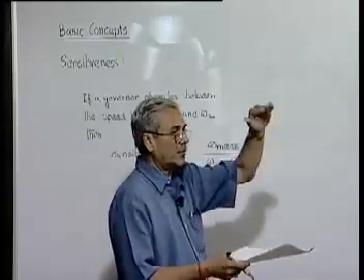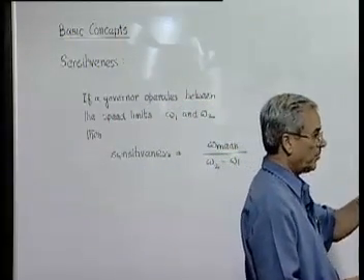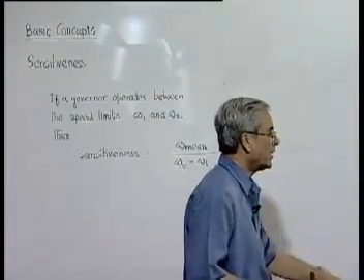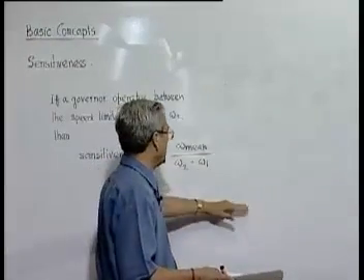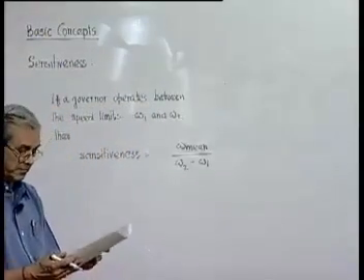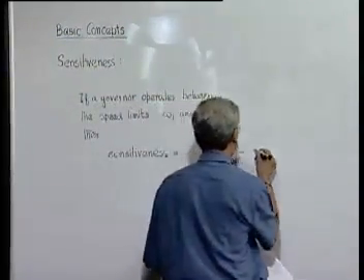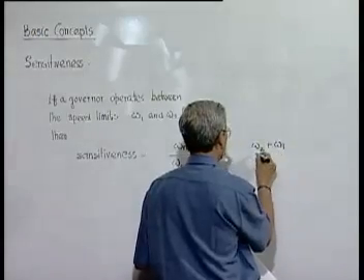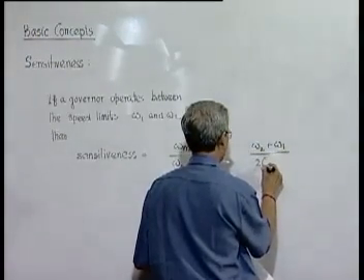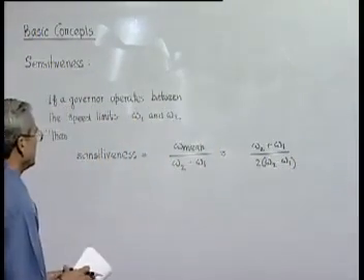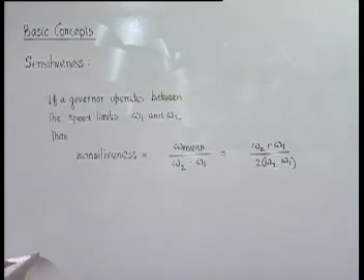On the other hand, if a governor has enough play, that means it operates at, say, 100 RPM at the lowest position and 700 RPM at the highest position, so that means there is a huge speed gap between the upper and lowermost positions of the sleeve, then its sensitivity is very less. Now, of course, omega mean is approximately omega 2 plus omega 1 by 2. So this can also be treated as sensitive. If you know the maximum limit, you can find out this.